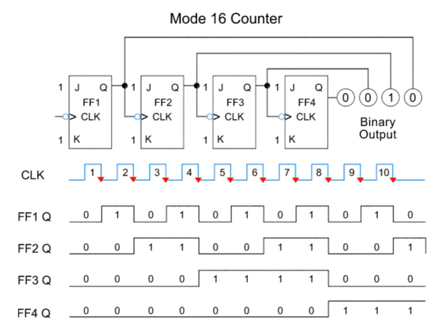Let's observe how a sequence of 10 clock pulses will ripple through a series of 4 flip-flops in this 4-bit counter. As we have shown, the first clock pulse generates a binary output of 0001, and the second, an output of 0010.